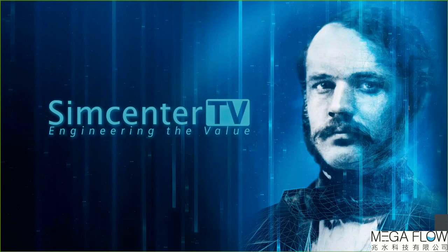Sure. To be totally honest, for steady state simulations with the new automatic CFL, we're able to converge within maybe 500 or 600 iterations. That's really, really fast. For steady state, I need a bit more testing on my side, but I don't see a big benefit here. I would consider AMR really a game changer for water management applications.